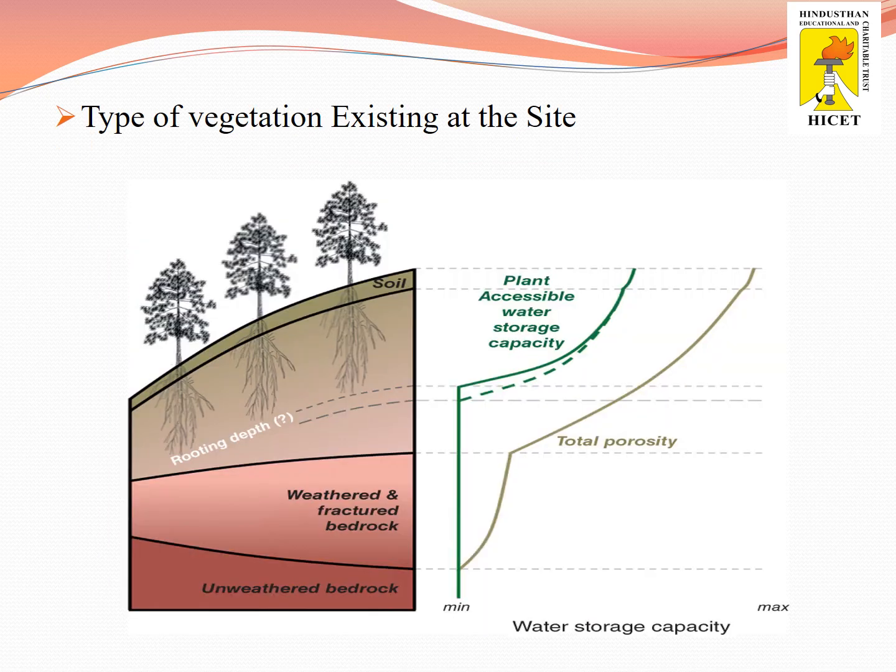Next one is vegetation. It gives a clue to the geotechnical engineer about the soil. If taproot trees or plants are available at the site, we can assume that the particular site has loose soil without any major or big rocks in it. If fibrous fruit plants or trees have grown, then we can guess there is rocky soil or soil of high density available there.